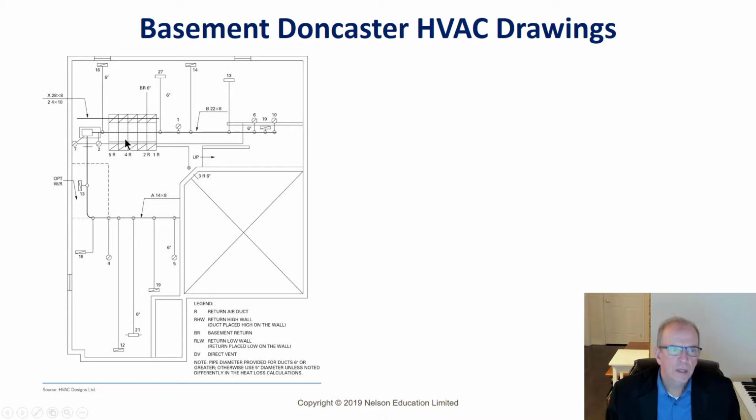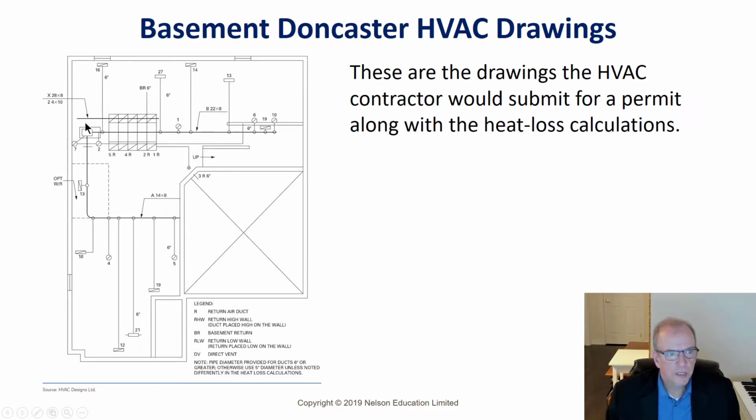And then the type of blower that the furnace has also dictates how easy it is going to be to get that warm air to the various locations. That's why I was saying it's better to have a furnace more centrally located. If I put the furnace back in this corner of the house, the far corner would be freezing. It'd be very difficult to get the air all the way to this corner. So you want to make sure it's located where it can at least branch out to the two areas that you're distributing to.